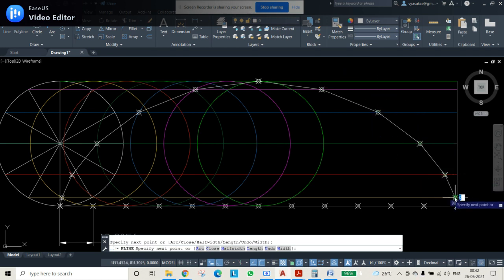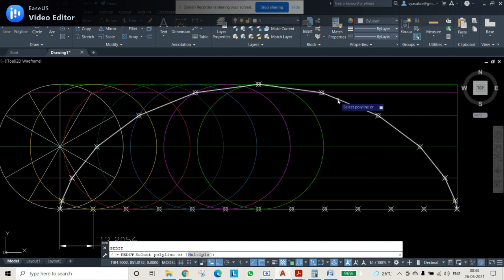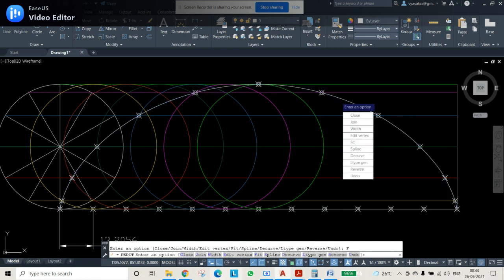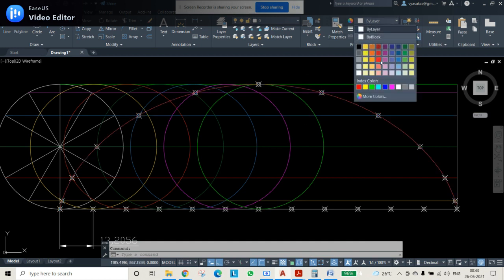It's not necessary that you should select the points first and then give mirror image and then go for the drawing of the curve. We can draw the half curve beforehand itself, and then you can mirror image the curve directly. Then PE enter, because it is done with the polyline. I'm fitting it like this. So once it is fitted, then select this line and give some color.